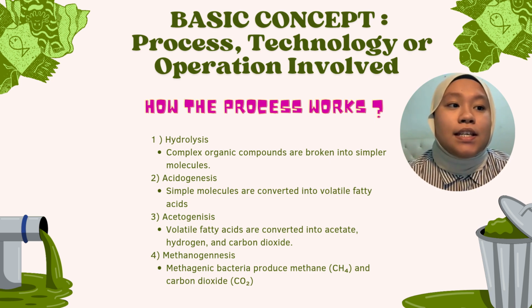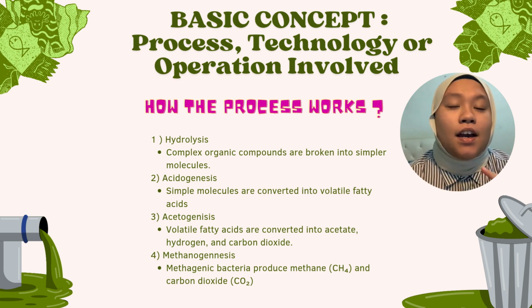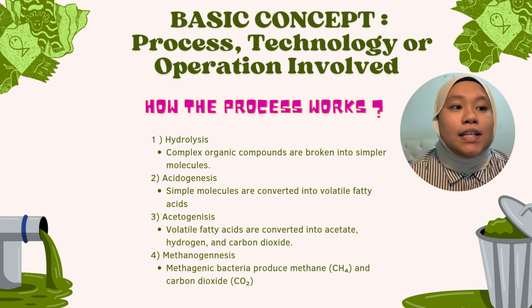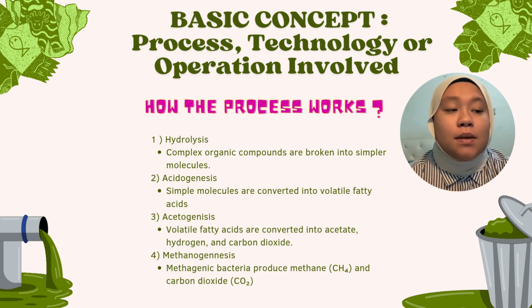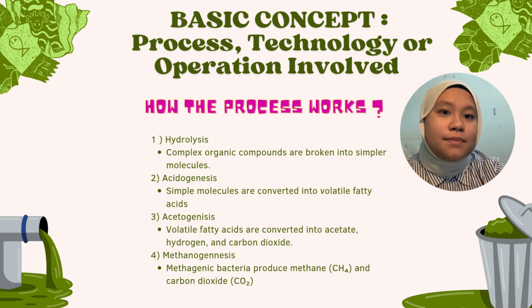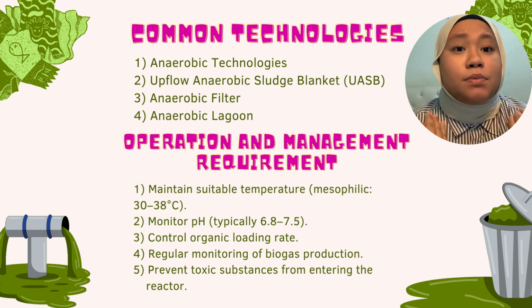The third one is acetogenesis, where volatile fatty acids are converted into acetates, hydrogen, and carbon dioxide. And the last one is methanogenesis, where methanogen bacteria produce methane and carbon dioxide. So, what are the common technologies that we use in our treatment process?